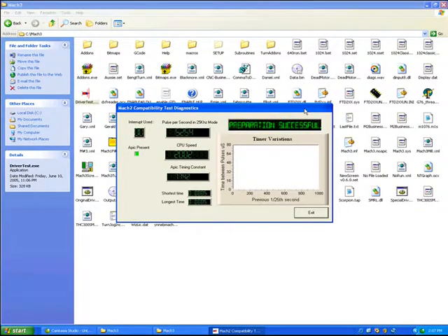If you get a waveform which is terrible, one which is not a straight line like this one gives you, but large spikes all over the system, or you may find you've got noise going up to this level and just periodically messing up your waveform, then you need to run a file called optimization.txt. This is a text file which has several steps in it which can help you to remove processes in your computer that Mach 3 is having a problem with.